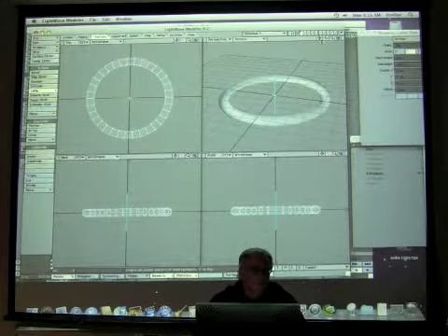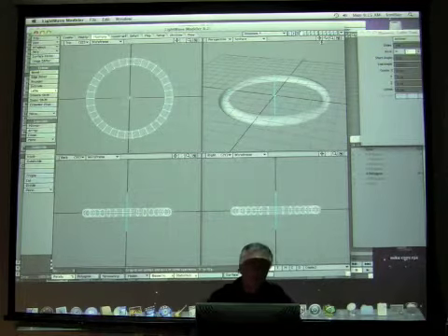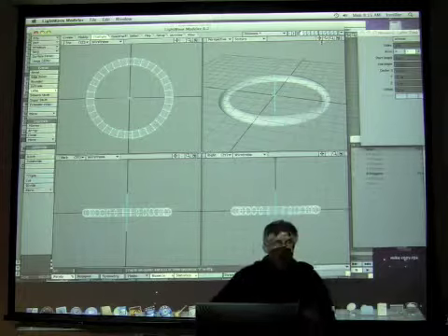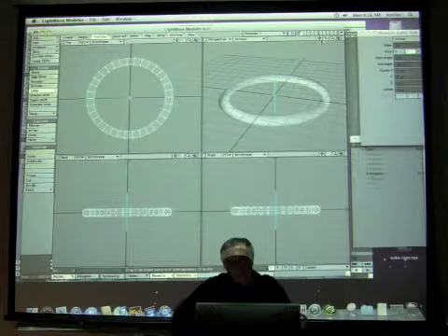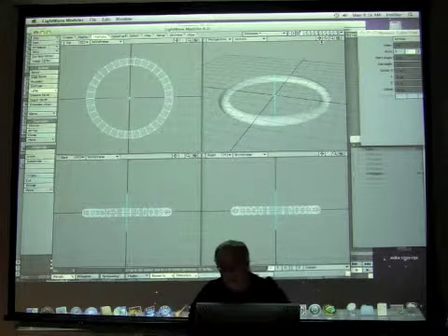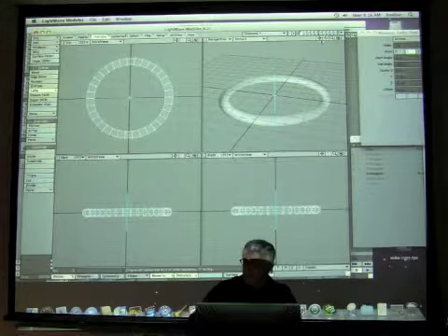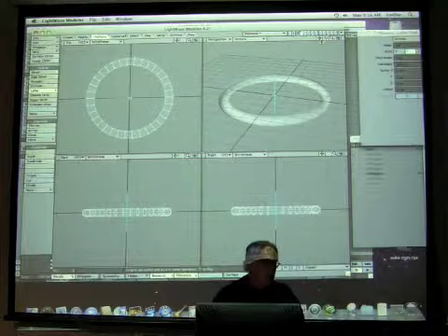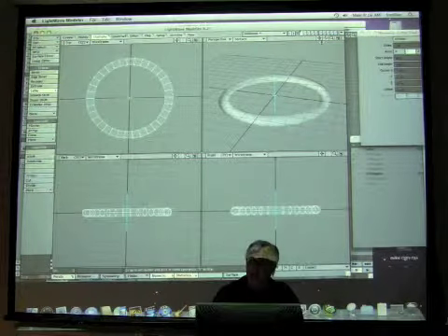Yes or no? No? Okay, watch what happens. If you lathe or extrude the wrong way, remember I started with a polygon that was one-sided. It's not double-sided. So if the wrong side is facing out when it's lathed, it really looks like it's inside out.